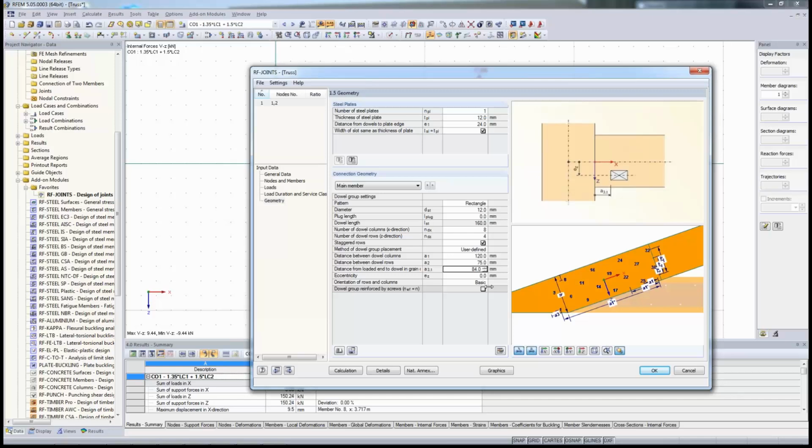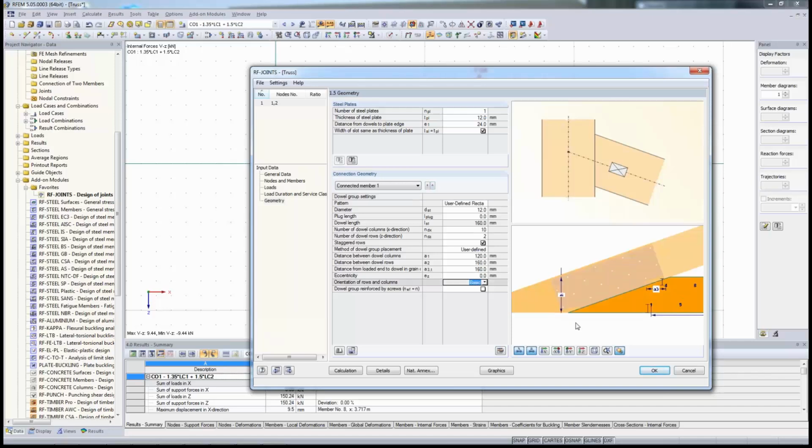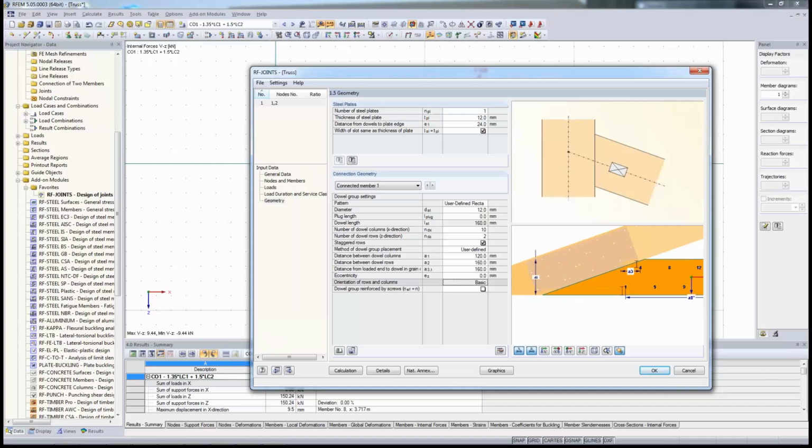And as I had problems with A42, I can also move the whole structure in the X direction, let's say about 14 centimeters. And as I also had a problem with the tearing on this side, with 98% loading, I'm going to choose a little eccentricity just to have it lifted more up here, and then switch to connected member, have a short look at the demonstration.